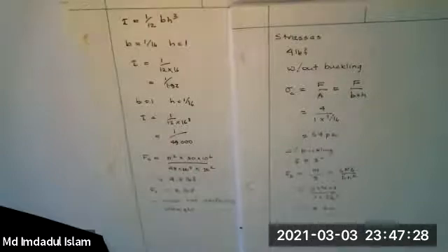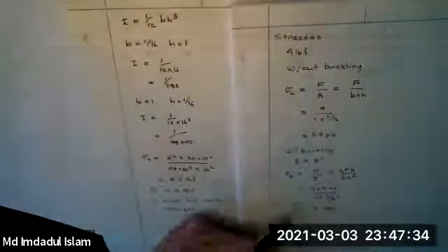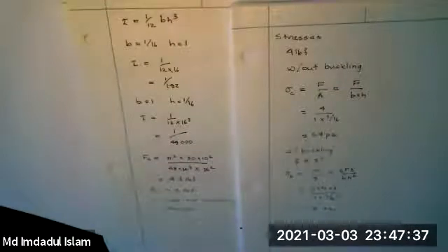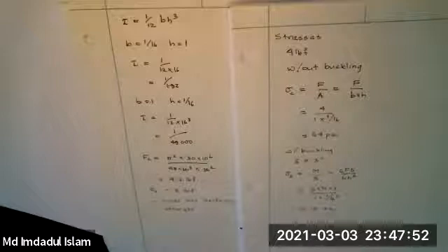This is a piece of steel, and I don't know what steel it is. Probably got a yield strength of about 30 KSI. So this is below yield. And so if I don't put too much force on it, I don't yield this structure, but the stresses are considerably bigger, order of magnitude bigger. I don't particularly want to do this, but if I pushed on this hammer, I would get the thing to yield in the middle, and then I'd have a permanent kink there. I could perhaps straighten it out too, but it wouldn't take too much to make this thing yield. So this is a key concern about buckled structures.